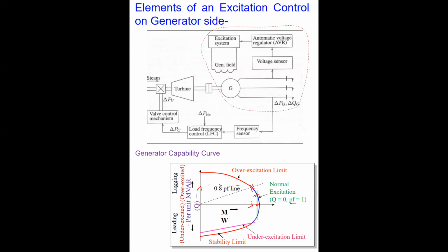So again, it is also important that, since I said that the generator is overexcited, if you have the generator overexcited, there will be some amount of active power and some amount of reactive power flow from the generator here, right? Anything on this one? So that is the operating region. You may have your generator operated somewhere here, you may have it over here, but let's say you operate your generator here. What does this mean?